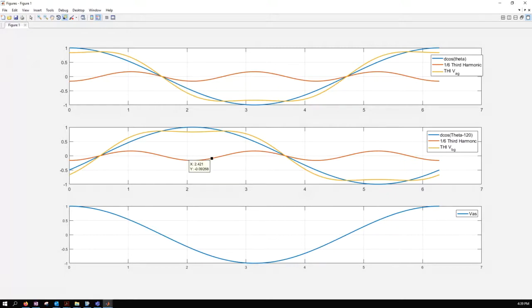It's pulling this down, and when you actually add the two together, your VBG, third harmonic injected VBG, looks like that, right? It's not reaching 1, so you are not hitting the full VDC, even though in your sine triangle case, it's reaching that max. Your sine wave is reaching that, right? But the third harmonic component is pulling that down slightly. Okay, now,